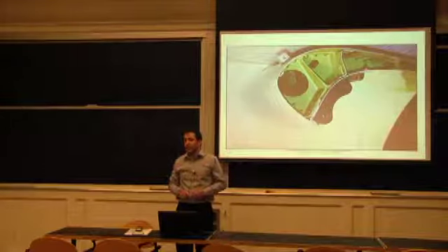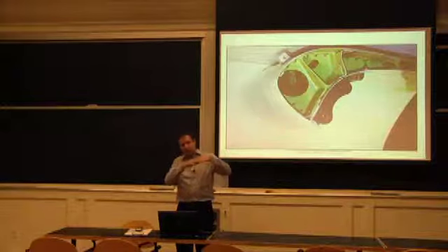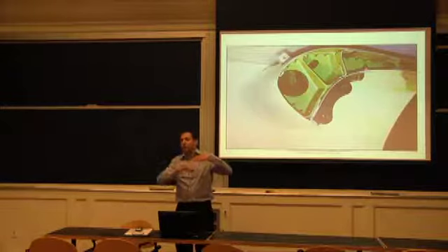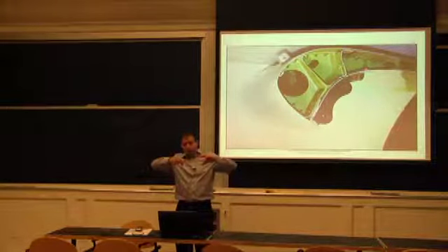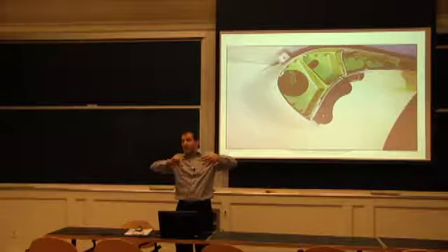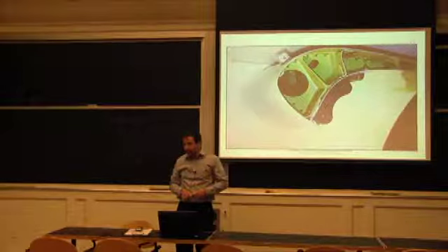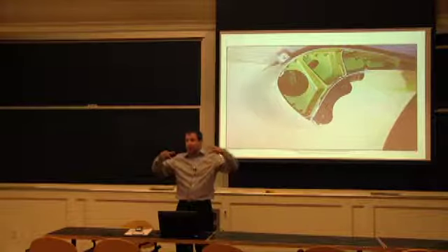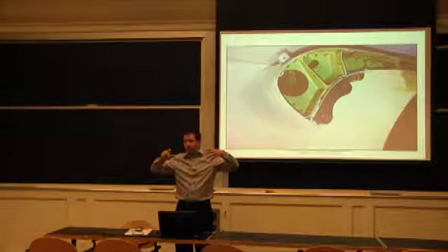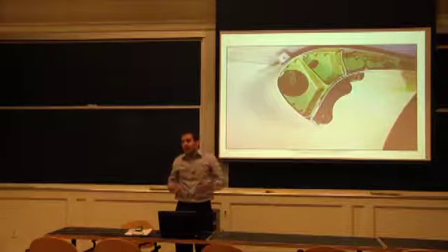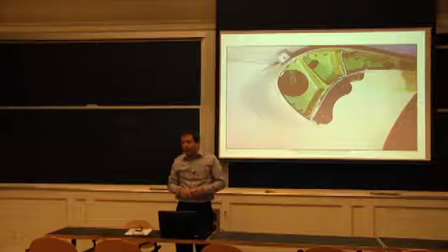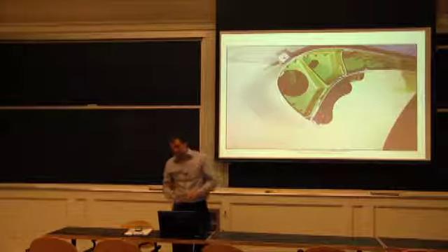And that's how you get shear stresses between your skin and the honeycomb in the back, just by the wing trying to tear this. And there's only so much from a design standpoint that you want to allow for that torsional rotation, because otherwise you don't really get the attack angle you were designing for. So there's a lot that comes into every single piece.